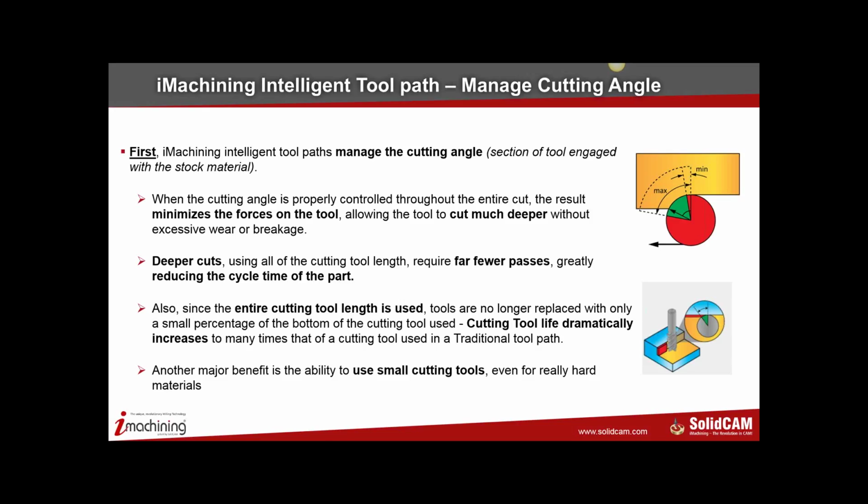sales tool, is to collect the chips, okay? To collect the chips, and at the end of the cut, display the chips in front of your prospect or in front of your customer and ask him to measure each of these chips. He will be surprised that the chip thickness of every chip, irrespective of whether it was cut in the corner or whether it was cut on a straight line or a profile, is the same. So when he says the chip looks to be the same, you should tell him, look, the chip is the same means what? Means the load on the tool has been constant throughout the cut.